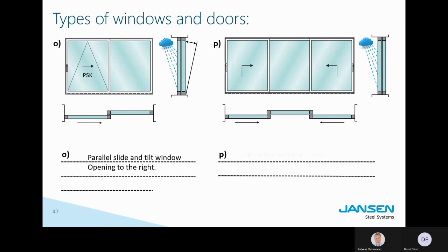The market standard are the lift sliding windows, where you have a lifting mechanism and then you slide the whole thing on rolls. This is actually what is built today. Terrace doors. Huge elements. We can build them either on Janisol or Janisol HI. And we can reach huge elements here, 4.7 by 3.2 meters, 600 kilos per wing. So we can achieve quite a lot with this type of opening window.